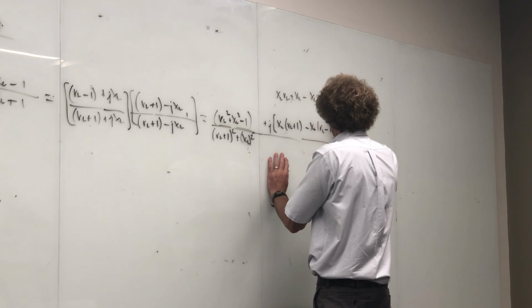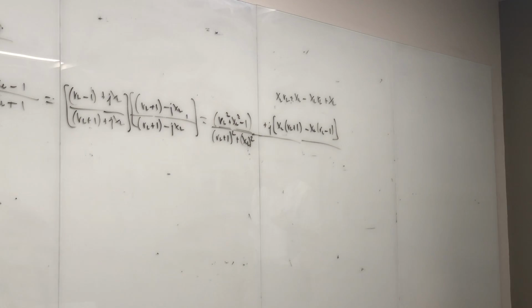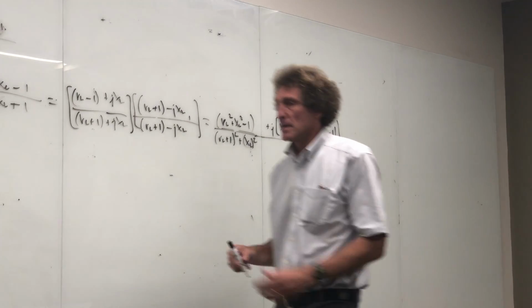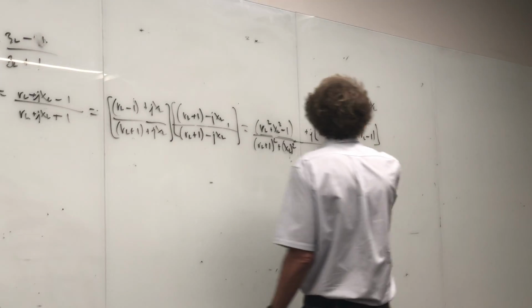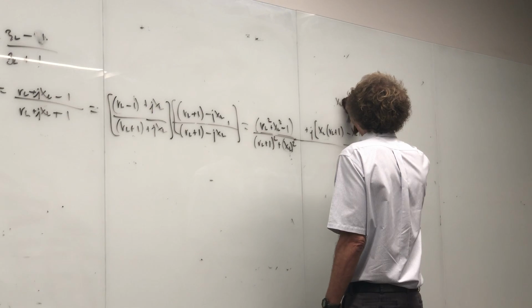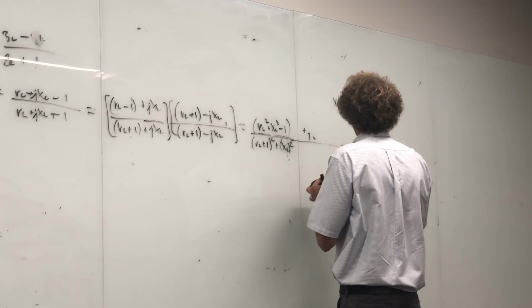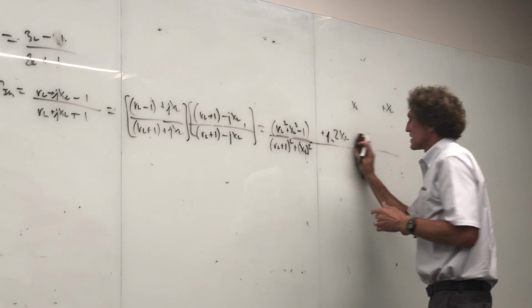And then it's going to be plus X_L. You follow me? What do you see happen? X_L R_L cancels. That's right. This goes away, right there. So really, I can replace this whole thing by j2X_L. And I'm using that term X_L.